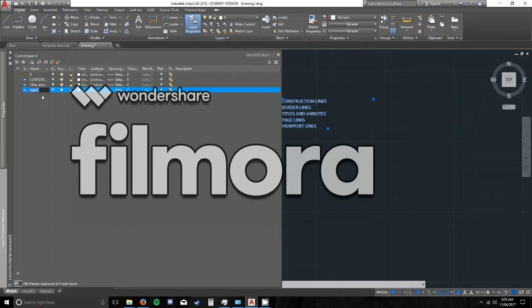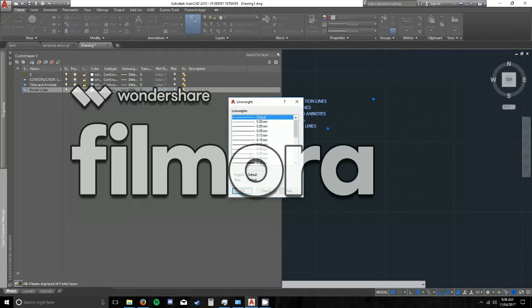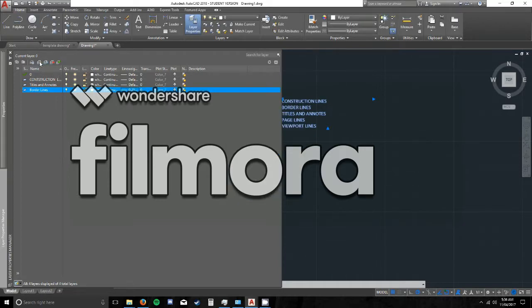For the next one, border lines, we will change the thickness of the lines a little bit. The line weight, we will change that to 25 mil. This will help us later when we create our title block, so just keep that in mind. And then for the last two, we'll create page lines and viewport lines.